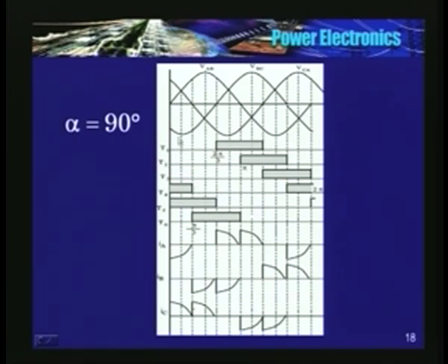Now, if you see at the zero crossing of omega t, T4 and T5 are gated, or a trigger pulse exists for T4 and T5, and VCA is positive. For 4 and 5 there are trigger pulses. Can they conduct? Let us see the equivalent circuit.